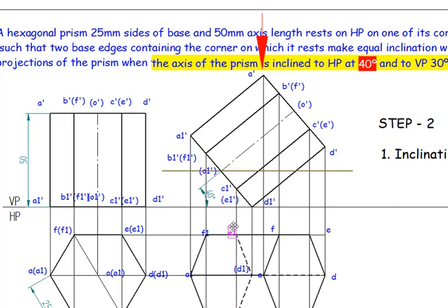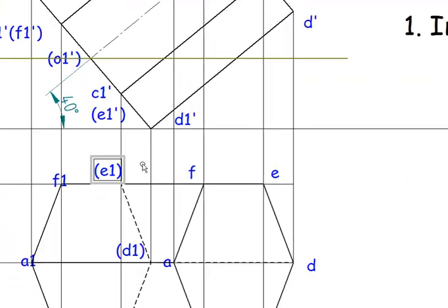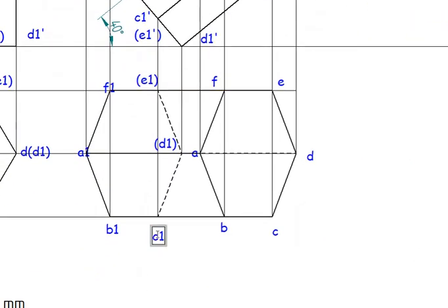So that one is also going to be E1 to F1, a dotted line, but it is going to be dominated by thick visible edges, that is nothing but F to F1. Similarly, E1 to E is again a hidden line, but again dominated by the top face. F to E is a visible edge. Now we cannot represent those dashed lines, but we can represent them by keeping the annotations inside the bracket. So C1 will also be inside the bracket.